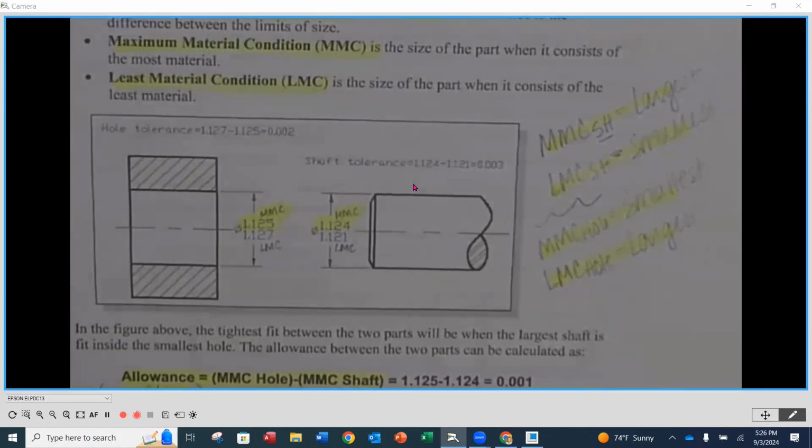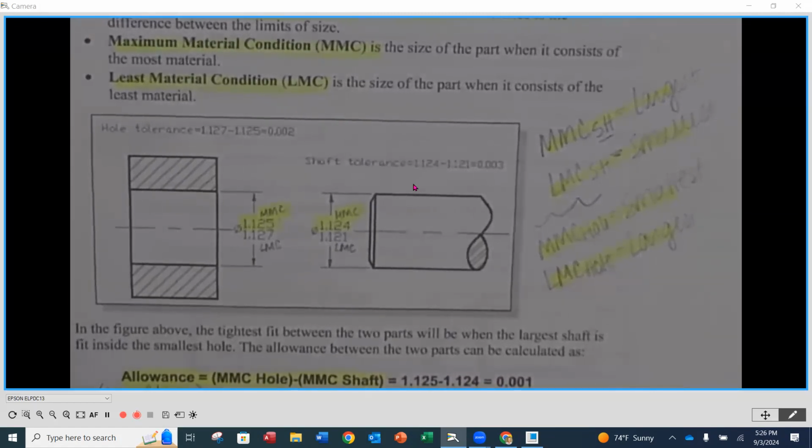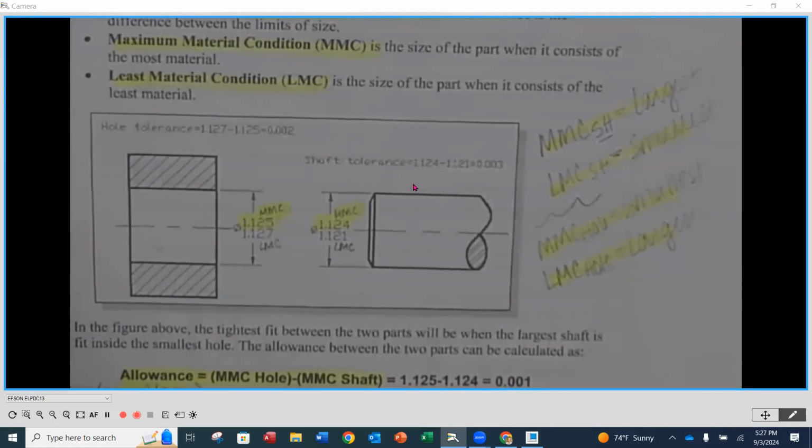So that's the reason. You want to make the hole smaller, you know, the sizes on top so that you can only make it bigger, but it also happens that way because of the behavior of the drill as it dulls. Does that make sense to everybody? Do you kind of remember that from manufacturing processes? You think as it would dull, the hole would get smaller, but it kind of works in the opposite direction.